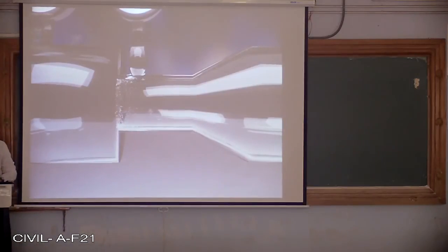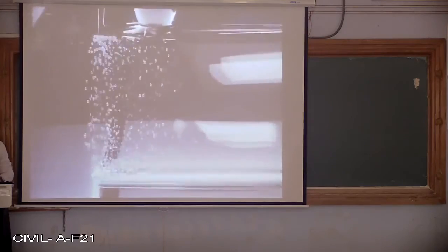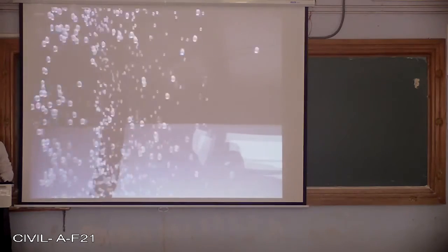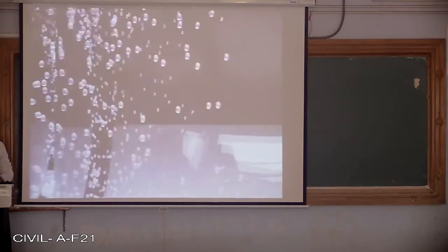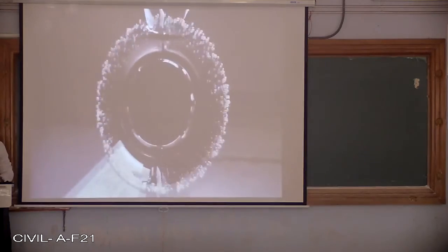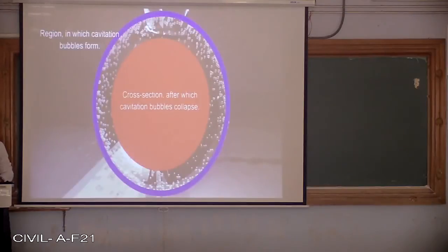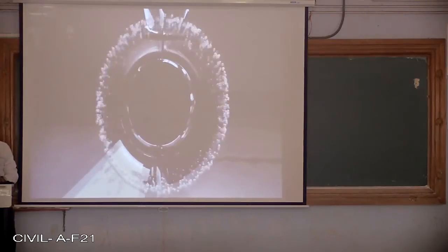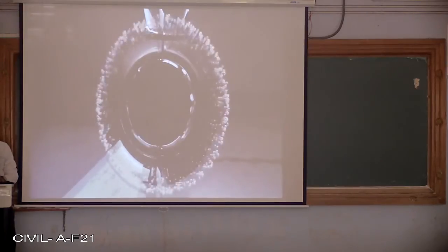50,000 times less volume after having condensed to its liquid state. The collapse of each bubble is a spectacular event and emits pressure shocks. Pressure shocks from many collapses result in an audible noise very characteristic of cavitation. The sound used now in the video has been recorded in an experimental setup similar to the one in the animation.